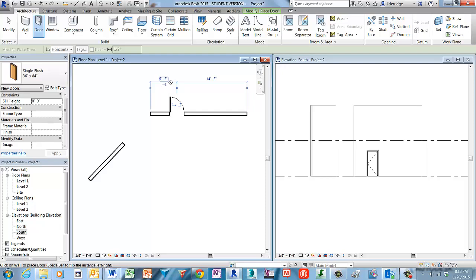And of course, you have temporary dimensions that are available to work with precision, so you can always select that value and type in a new value. Another way to work with dimensions is to drag the shape handle for the dimension witness line and set the context that you wish to work from, and then type in the value that you're seeking to relocate the door.